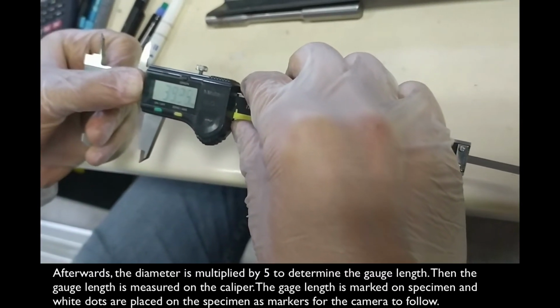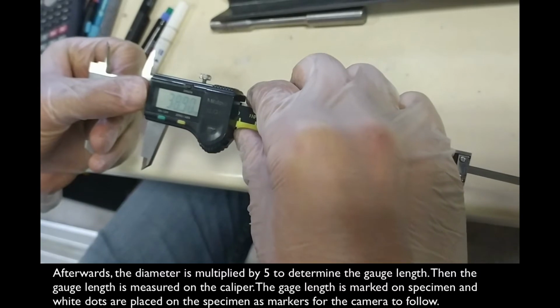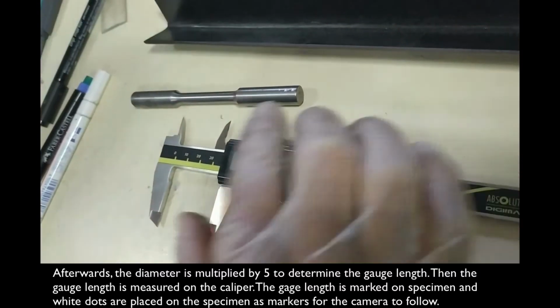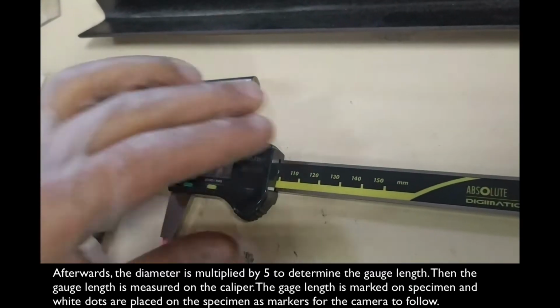After adjusting the caliper, the gauge length is marked on the specimen, and white dots will be placed on the specimen as markers for the camera to follow.